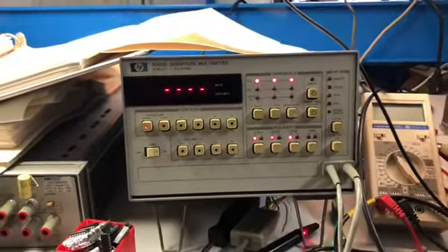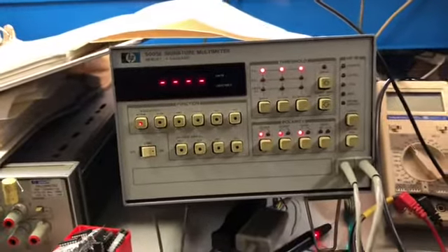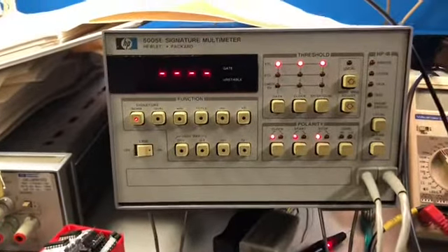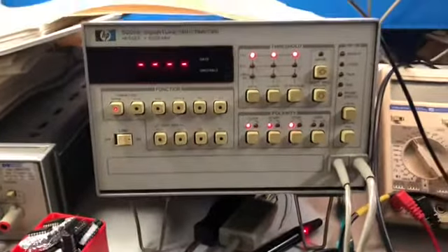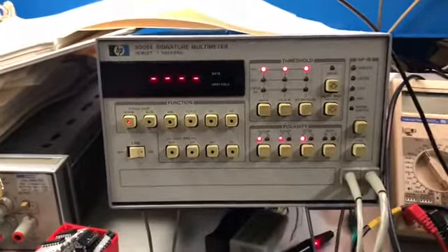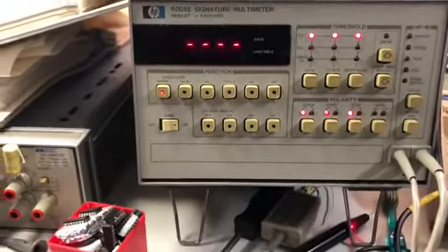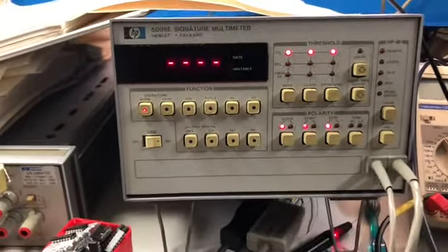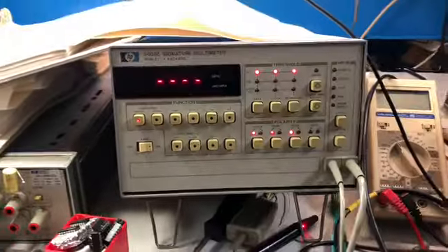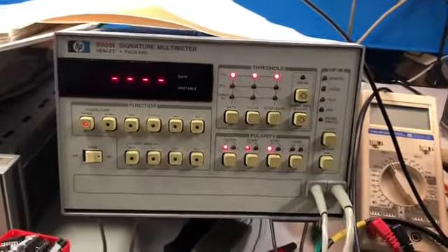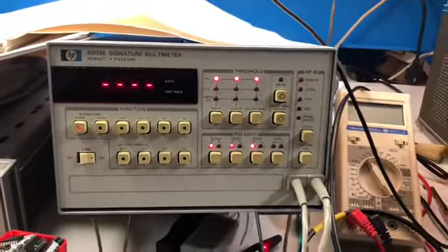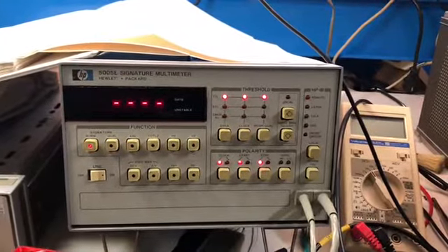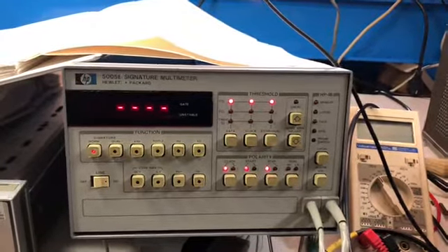Of course, I have also this signature analyzer, which is helpful, and you cannot perform troubleshooting on this unit without it, because in the service manual there are indicated and listed all the codes that you would find on the unit. Despite the use of these, of course, I have found that several codes are wrong. They are very close to the codes that should be, but not exactly.